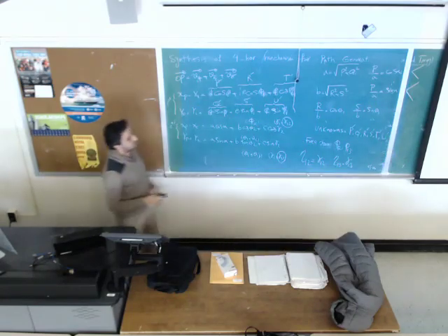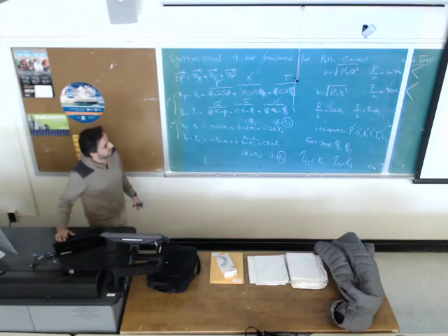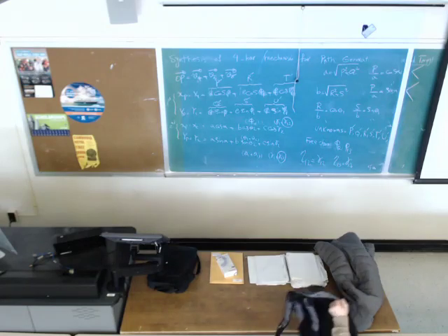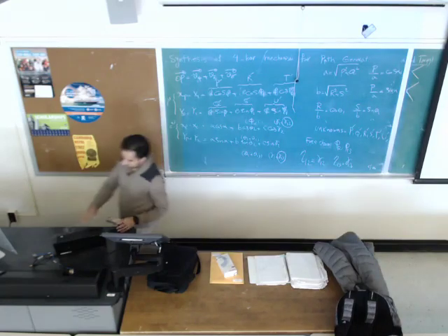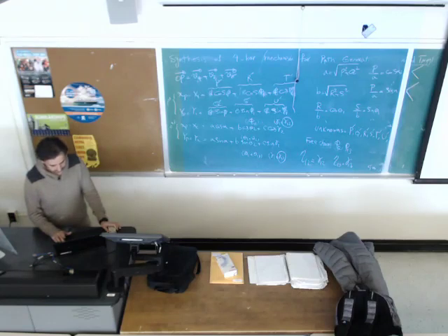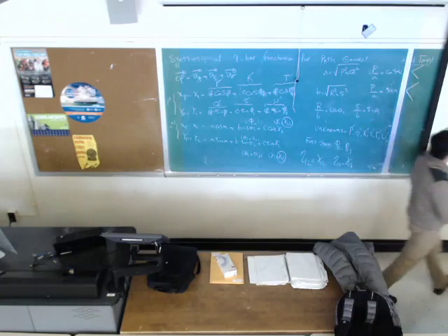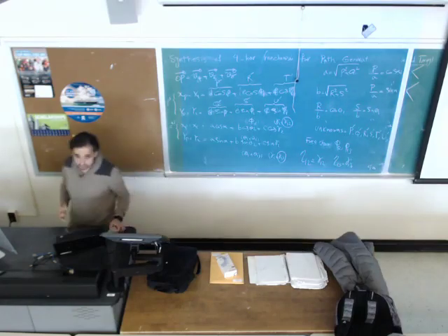So we solve for P prime, Q prime, R prime, S prime, T prime, and U prime. Then we can find D and beta, E and phi 1, F and eta 1. So if I ask you to draw or sketch the mechanism, you should first sketch the left and then right hand side of the dyad, and you are going to get the complete mechanism. And the mechanism is going to move point P from the first precision point to the second.